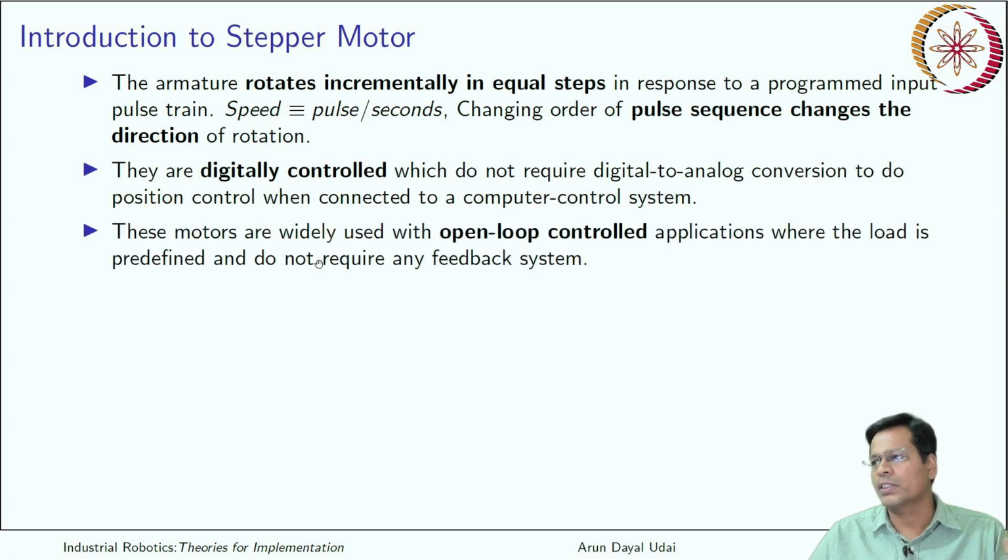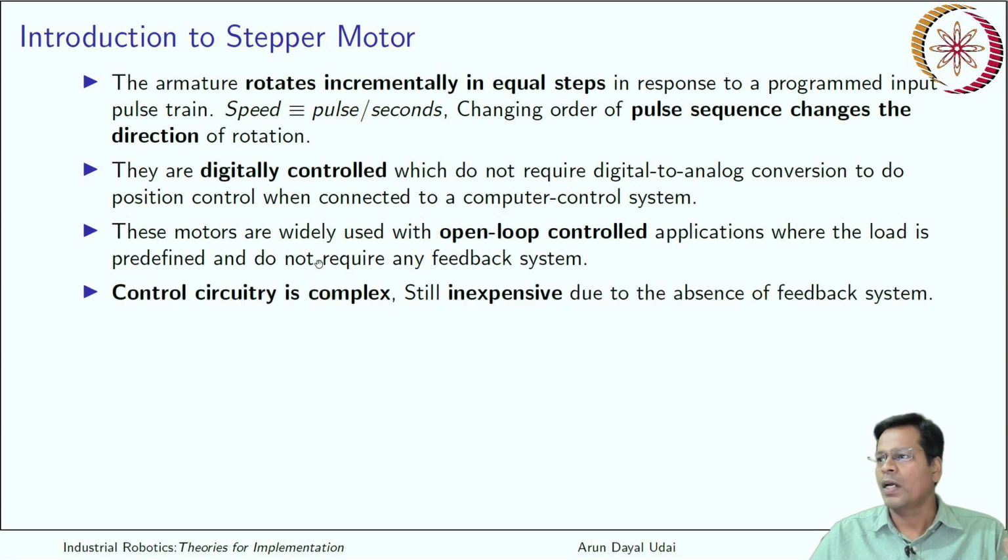These motors are widely used in open loop controlled applications where the load is predefined and you do not require any feedback system. The control circuitry is a little complex compared to a DC motor, but still they are inexpensive because you are able to do position control even without a feedback. The feedback mechanism is totally missing, and that is what keeps it inexpensive.